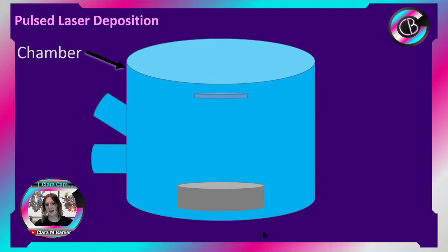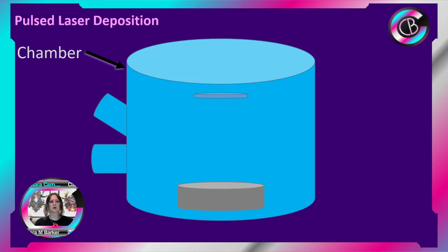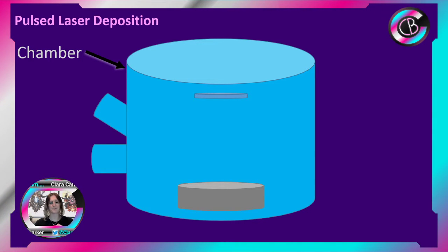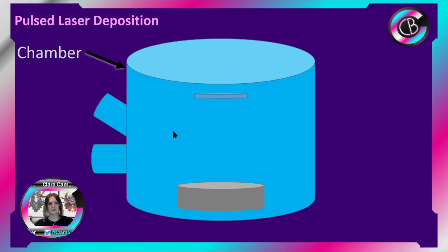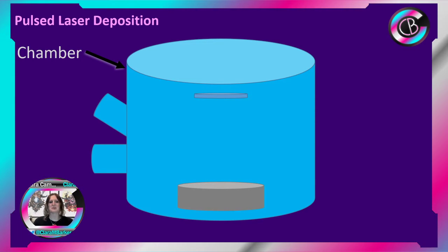and again we have the substrate. We have the substrate in there, and we have our target material. So this time, if you remember with evaporation, we had a crucible or a ceramic boat, and we melted our target material with that, our depositing material with that. In this technique, we actually have a thing called a target. And so this is basically a chunk of metal made of the building blocks that we want to use. And so it can be a metal, say, I keep on saying titanium as an example. So it can be titanium, but it can also be some sort of